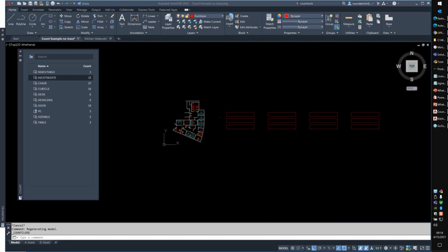For dynamic blocks and the count palette, does it show all visibility states, or only the ones that appear in the drawing? How does the count handle anonymous blocks, unnamed blocks from the clipboard, and other things like proxy entities and bound xrefs? Okay, it's going to ignore proxy entities and anything in bound xrefs. If you've bound an xref and it has the bound block names, you will see all of those block names in here. Anonymous blocks, that one I haven't worked with yet because I haven't actually run across a drawing that has an anonymous block, one of the U star blocks. Unnamed blocks, or the A star and the U star, but any of the $C from a copy and paste does get picked up.